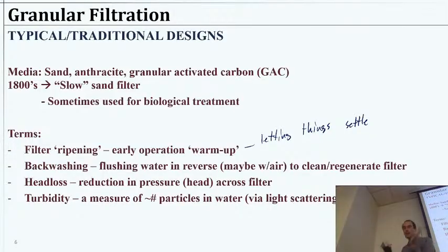And really, all of the math that we're going to talk about for this segment comes down to how we're managing how much water we're producing compared to wasting because we need to backwash. So it's almost all water management here in terms of, okay, we're producing this much with this many filters for this amount of time, but every 24 hours we have to take it off for an hour to do our backwashing process.